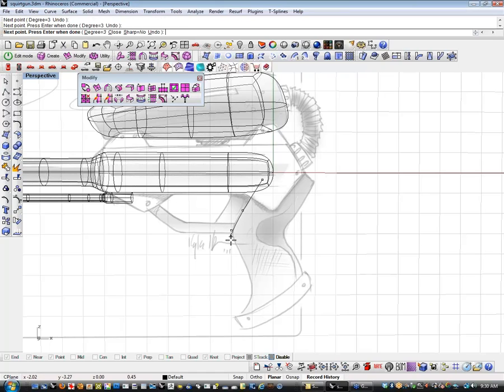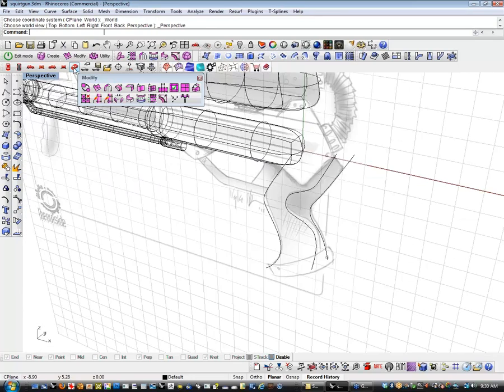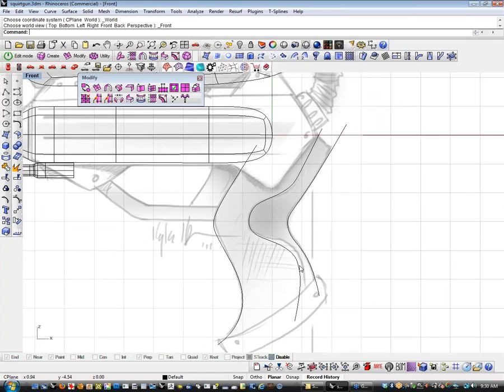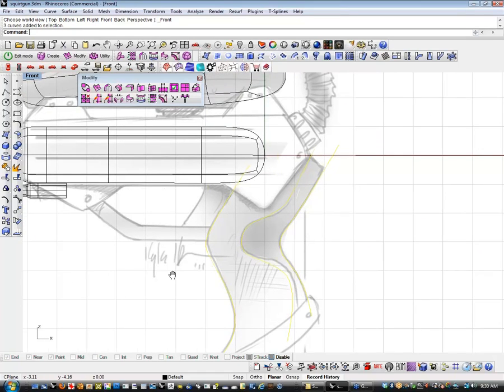I'm just going to start with some curves. These are just typical NURBS curves, and I'm just going to outline this thing roughly, and then where my thumb piece is going to be, I'm going to outline that in there like that. Now these are all flat. These are just dead flat. This is a paper doll. I'm a big proponent of paper doll modeling if you've seen any of my other demos.